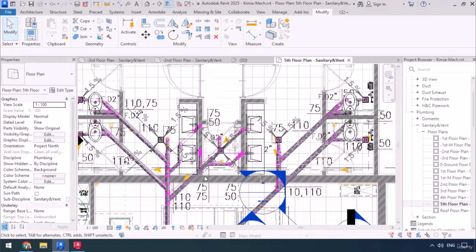Now the first vent that we place is going to be the vent pipes for the lavatories or the sinks. Those pipes will help us determine the elevation that we need to apply, because if we want to start from the vent pipes of the other fixtures, there is the possibility that we might get them mixed up and not know if they should be under the ceiling or above the floor. So starting with the lavatory pipes will make that a lot easier.